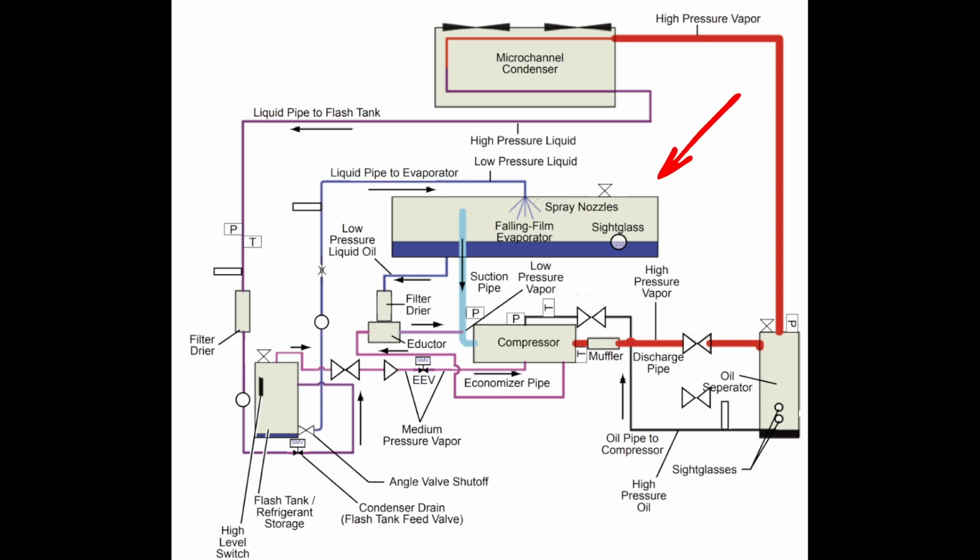And it's also where, when you get into the larger water cooled side of the world, eductors are very commonly used, or an oil recovery system of some kind is used very heavily. But historically, with air cooled systems, they're not. We don't use falling film or flooded evaporators as often. We are starting to now, and a YVAA does do that.